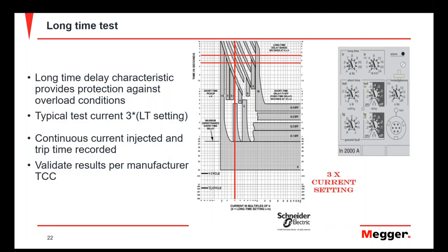So when we talk about the long time testing of a breaker, we're talking about the long time delay. And long time delay usually is set to trip over a period of time to protect against an overload function, as we talked about in the last couple of slides.